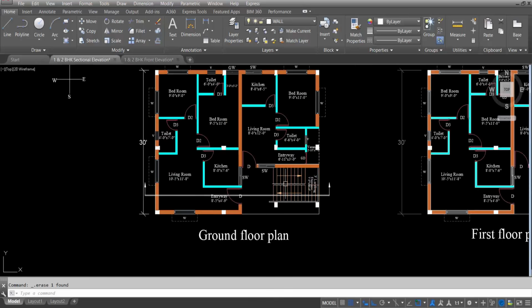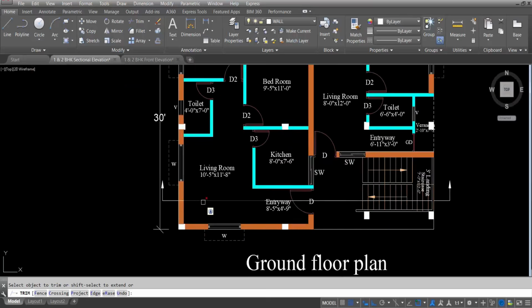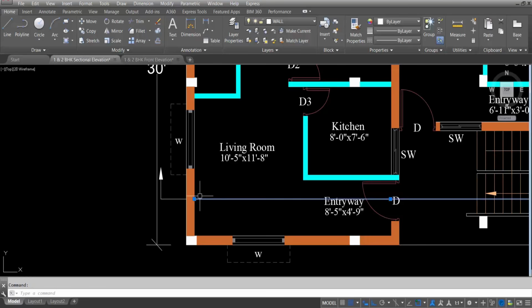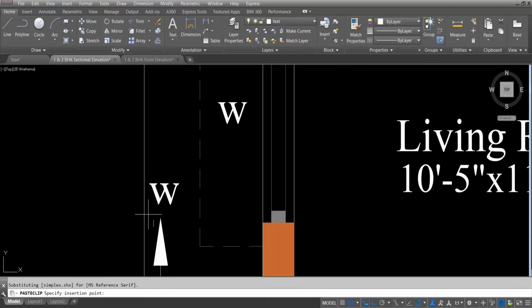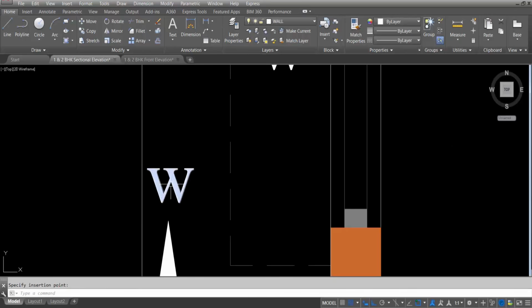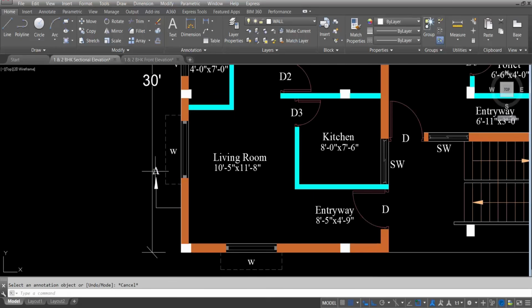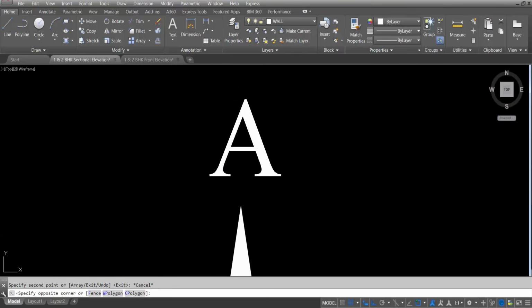So this is the section line, so this line is no longer required. So if you want, you can delete this. So how to delete? You trim from here and you trim from here and simply delete this. But we need one horizontal line here. So first I'll provide the number. This is section on AB. You can give XY as well. I'm taking here section on AB. This is B.